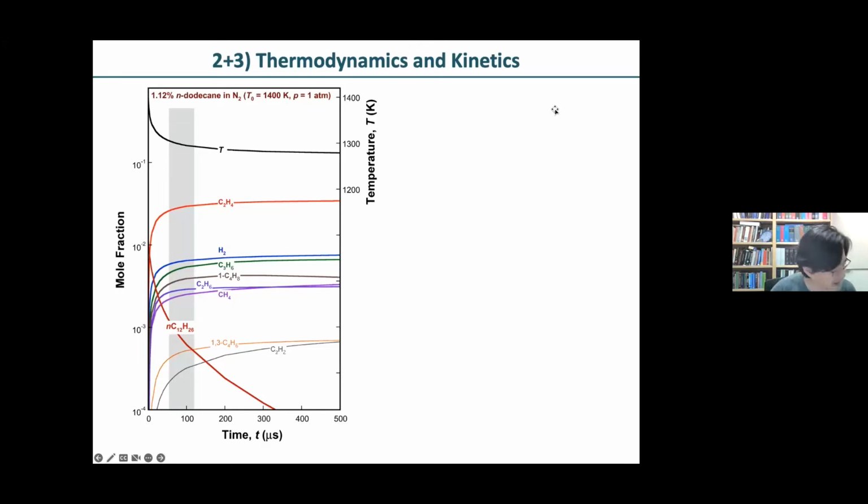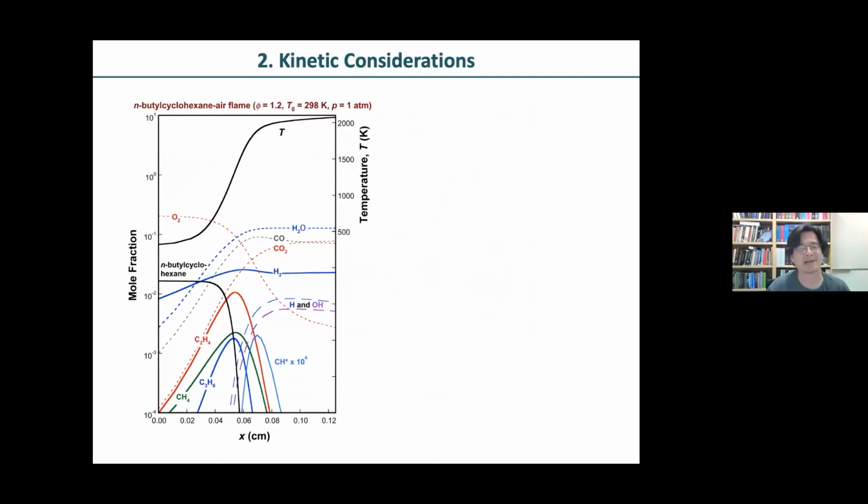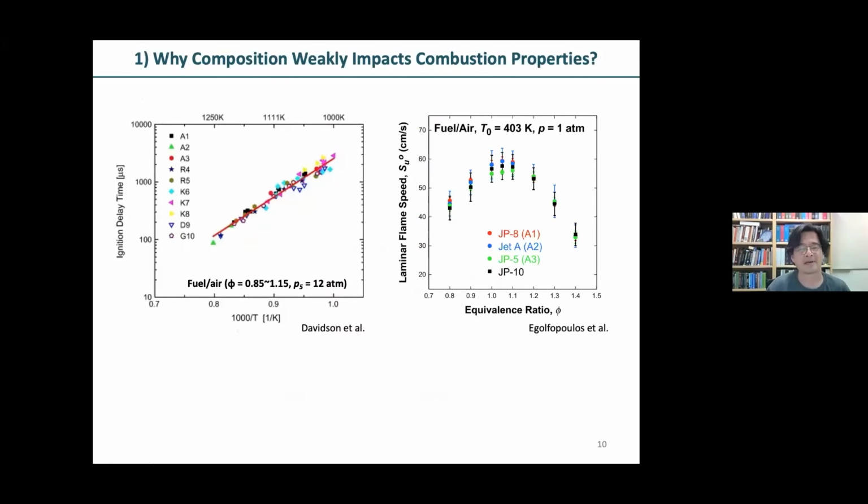That's my speculation, but from our experience, as you saw earlier, basic combustion properties, legacy properties, ignition delay, flame speeds, among diesel fuel, gasoline fuel, and jet fuel, are all the same. There's no fuel sensitivity, no composition sensitivity. It's this chart I showed you earlier. Among all of the fuels we tested, from jet, rocket, generic kerosene, diesel, and gasoline, they all fall on the same line.